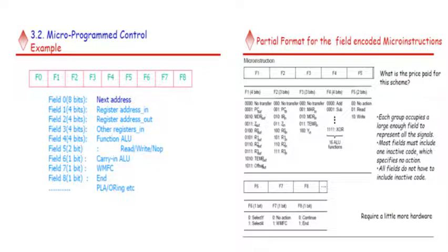The figure shows a complete format of the microinstruction. This format is an expansion of the format which was shown previously. Using such microinstructions, we can implement the microroutine. The revised routine has one less microinstruction. The branch microinstruction at location 123 has been combined with the microinstruction immediately preceding it.